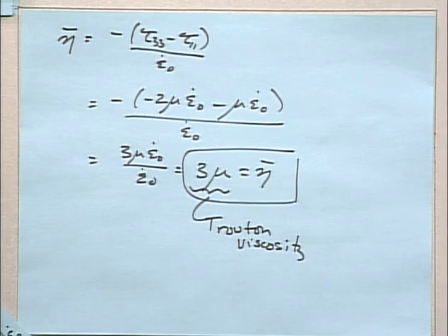So at least if you're puzzling, it should be over the details of the constitutive equation, not over how to start. How to start should always be, I know the velocity field. When I'm predicting a material function, I always know the velocity field. And since the constitutive equations will always have velocities in them somewhere, plug them in where you see velocity and then worry. You'll see that as our constitutive equations get more complicated, there'll be something to worry about in terms of making that calculation, but that's always the way it starts. You're always predicting a stress. Okay, so we did that.